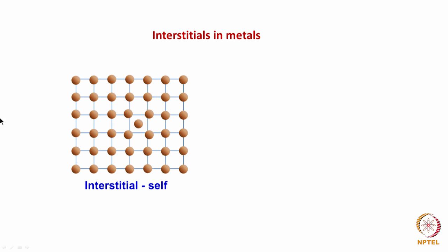Okay. So in this particular case, the atom can occupy the center of this lattice, or the unit cell, correct? Randomly it can occupy it. When it comes to that center, what is essentially happening? All other adjacent atoms will be shifted a little bit away from their equilibrium positions, because a lot of strain is being introduced into that region locally.